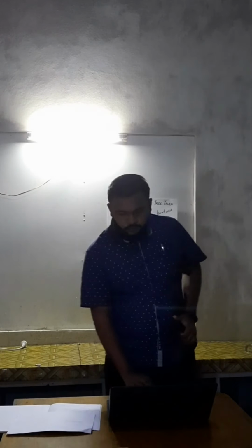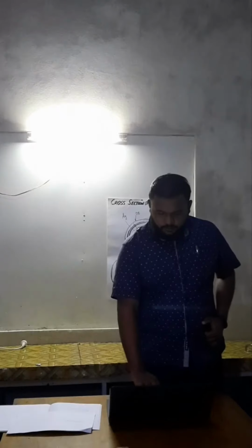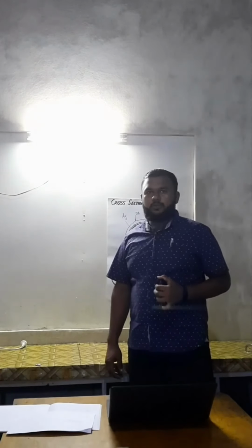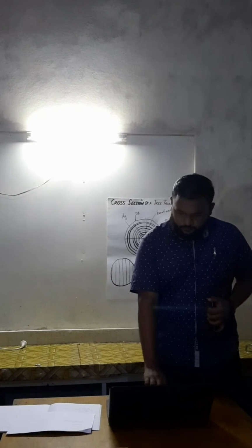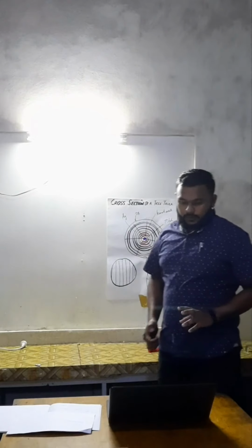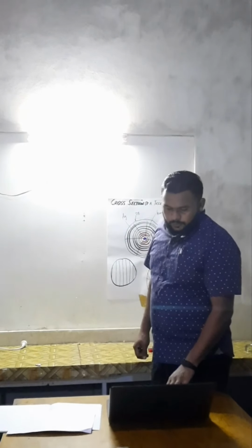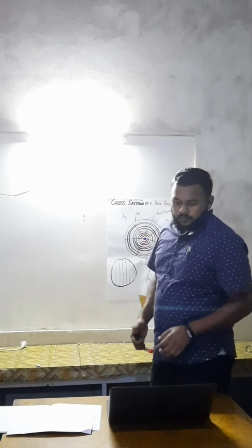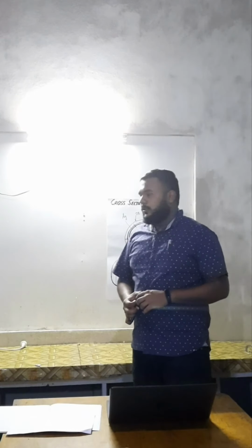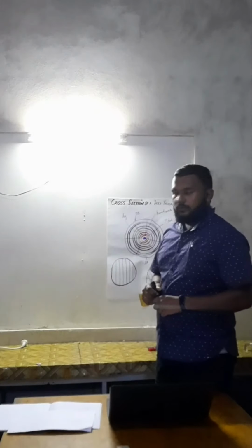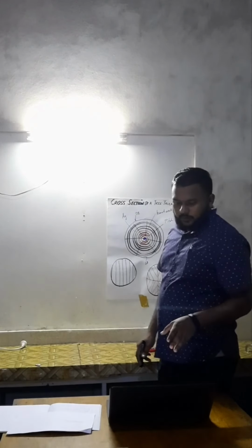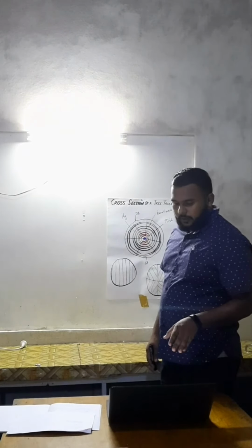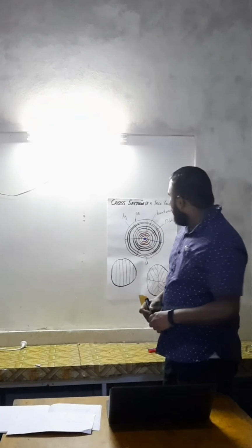And now we'll be talking on seasoning. Seasoning is a process of removing moisture content from timber, also known as drying timber. There are two types of seasoning. The first one is known as air seasoning or natural, where natural wind is used for drying timbers. In air seasoning, the timbers are usually stacked in an orderly manner.